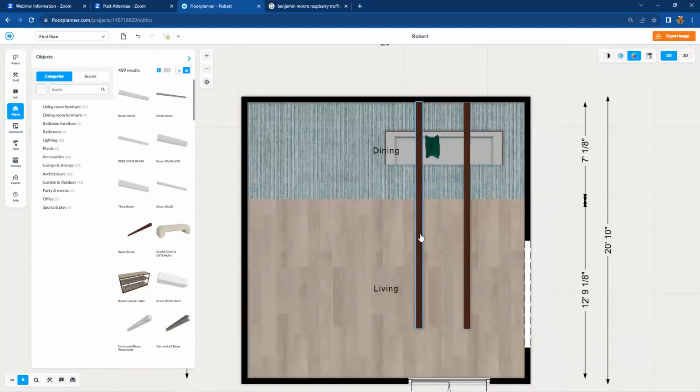You can actually cut below items above your head to make your two-dimensional plan, like a cut section at a lower height. If I go to 2D settings, it's in the general settings, where it says hide all above a certain height.